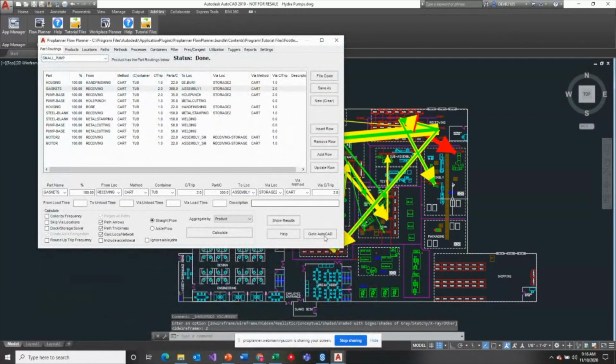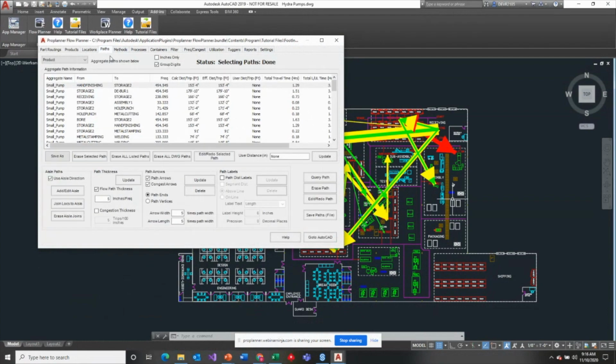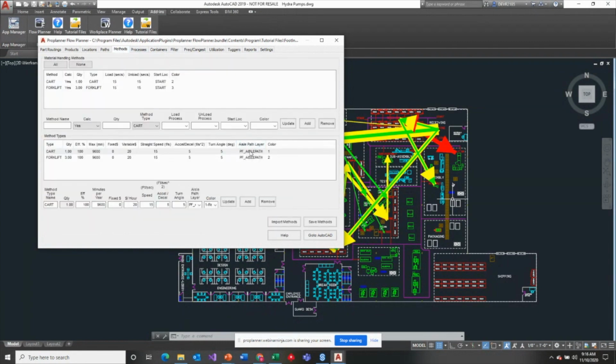The aisles are pretty straightforward. You can see these purple lines in here. I went into the software. There's a PES tab. I created aisles. But essentially what's important to note is the aisles are just lines in AutoCAD drawn on a layer. Now, what layer? Well, you specify the layer. So in this case, I create a layer called PF_aisle path in AutoCAD. And I use that same layer for both the cart and the forklift. I could, of course, create 2 different layers and draw lines on those layers. Okay, and then each device essentially goes to a layer, in this case, the same layer.